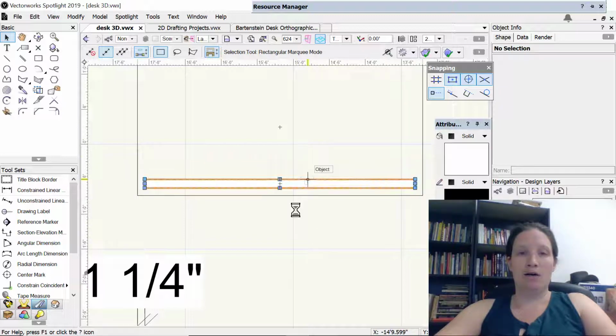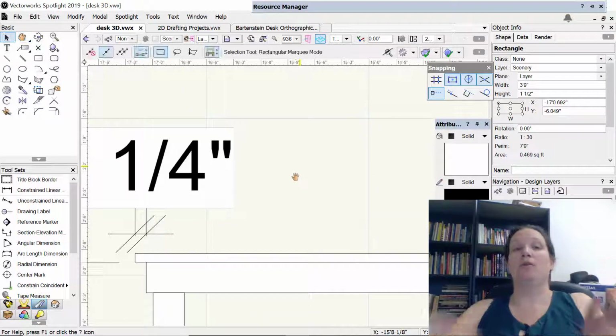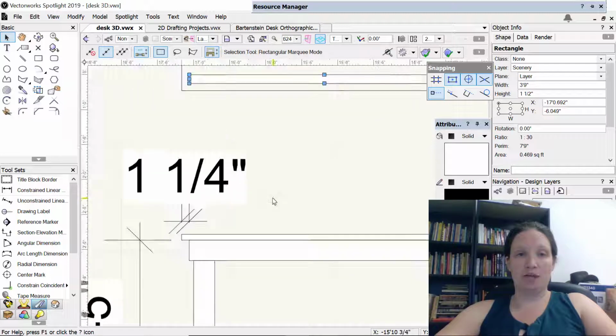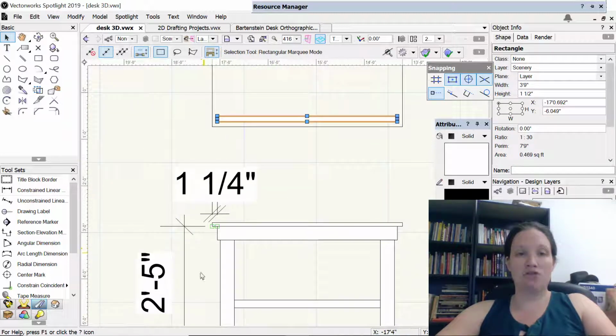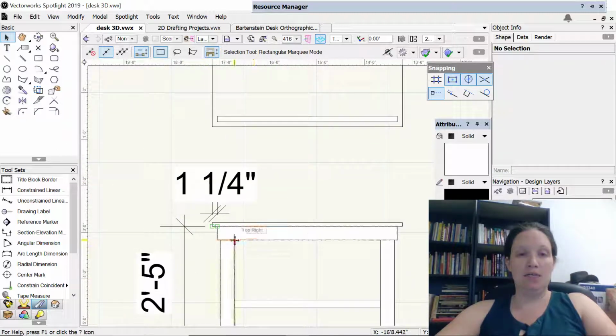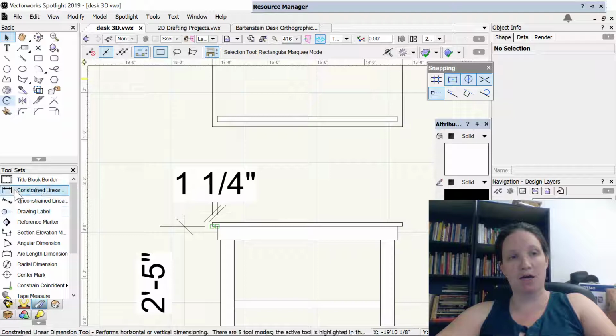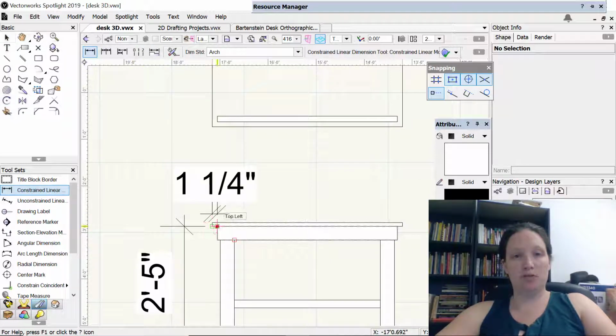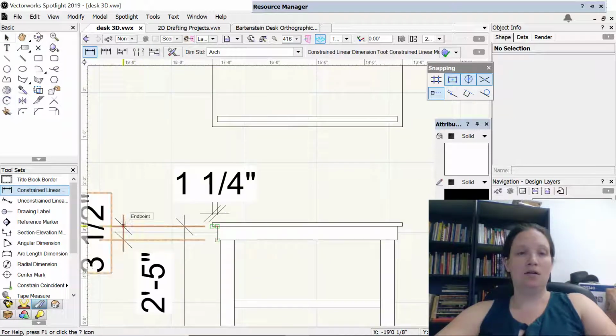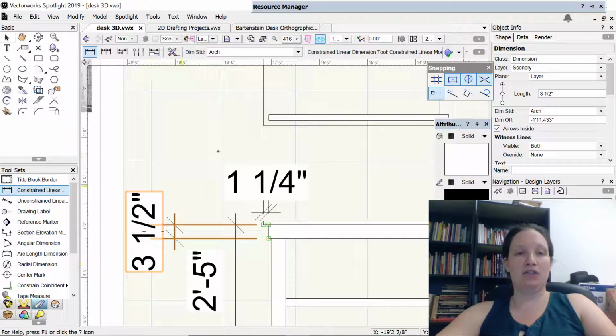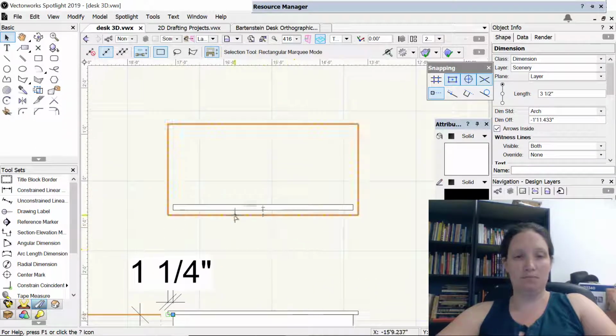All right. Now I'm going to extrude it. So I'm going to give it a height, another dimension, a third dimension, and that extrusion distance needs to be equal to how tall it is in side view. So I'm going to grab my linear dimension tool again, and that height is 3.5 inches.